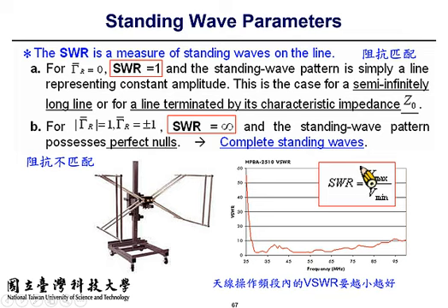To the far left, the VSWR value is relatively large, which suggests that the matching is poor, which means that the incident electromagnetic signal cannot be radiated by the antenna in the form of an electromagnetic wave.